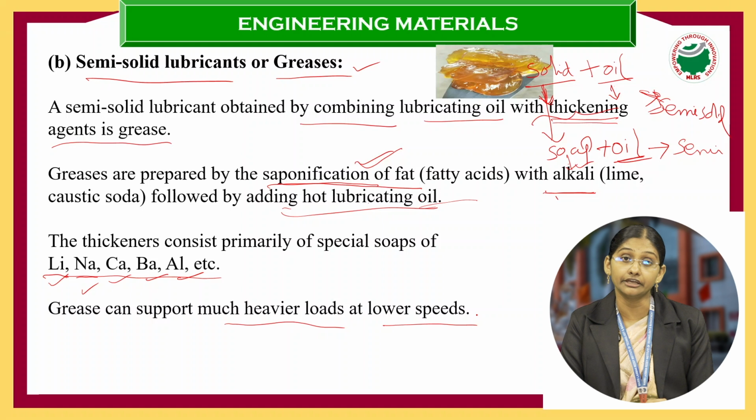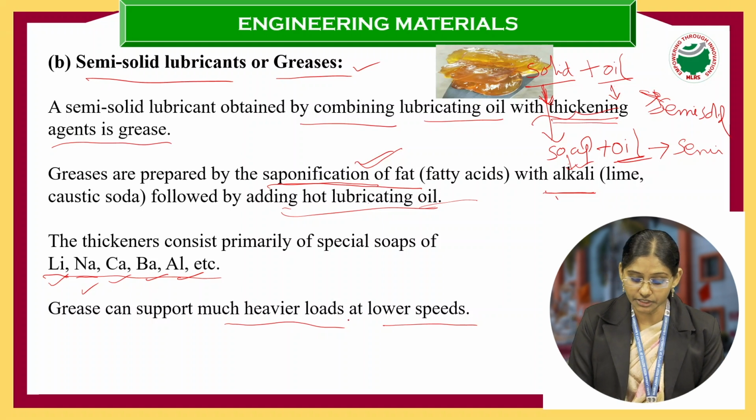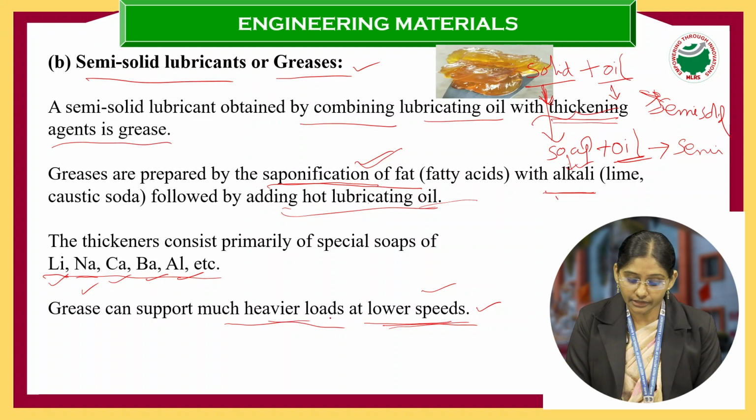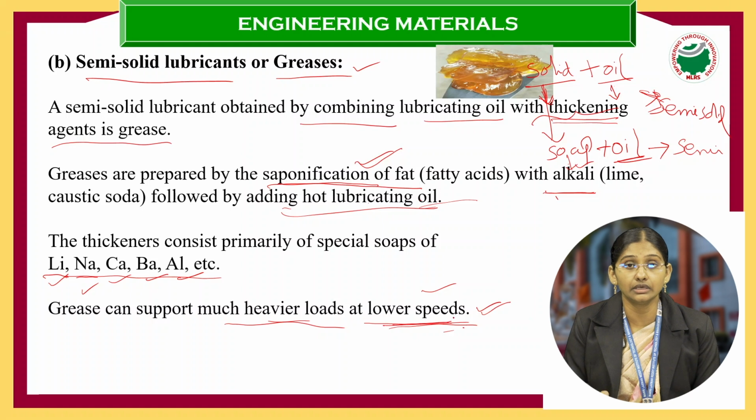Grease can support much heavier load at lower speed. Here we need to observe this. What is this lower speed? When the machine is moving with lower speed, this semi-solid substance, that is grease, can stay at one place for a longer duration. So heavier load, but the lower speed should be there, and the lower temperature also should be there. If the machine is moving with high speed and high temperature, this grease cannot be preferred, we cannot use it.